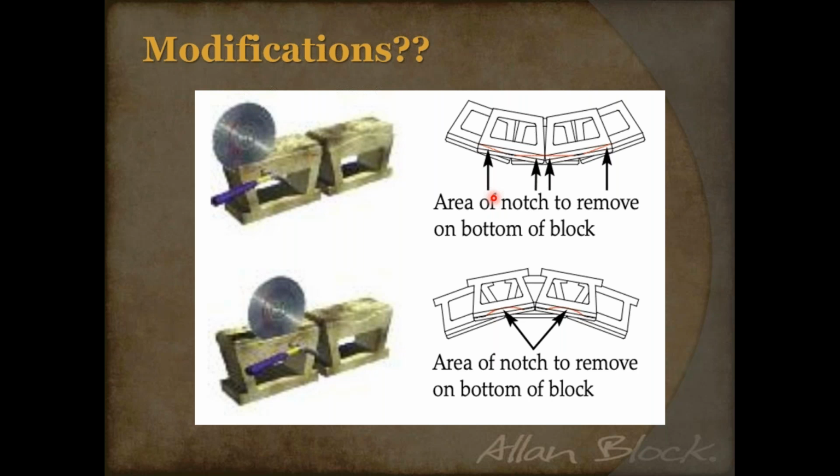So again, all aesthetics, non-structural, but another reason why I know a lot of contractors try to avoid the cuts by keeping their radiuses pretty large. You know, like I said, 10 foot or more, and now they've got nice fluid curves, and it's easy to make the product work regardless of the product. And like I said, if you're turning a radius with any segmental retaining wall unit that's 18 inches in length, you're going to have these pinch points out there. So be smart in how you do that layout, and that way you can avoid the cuts, which obviously cost you time and money.